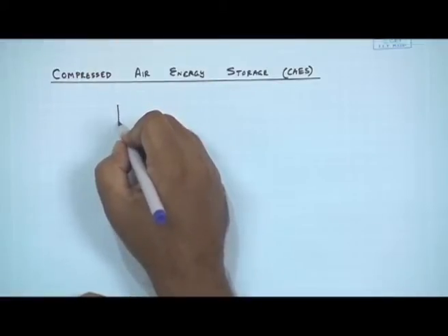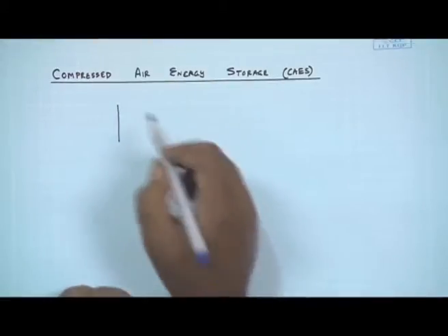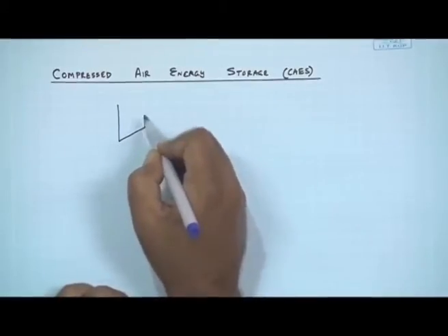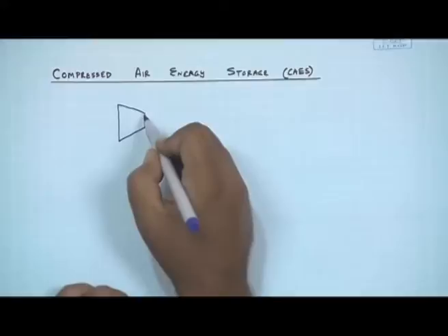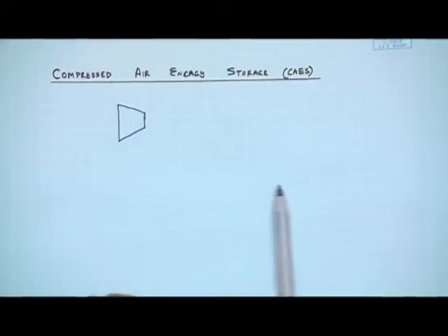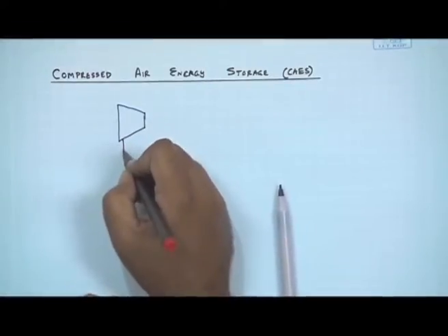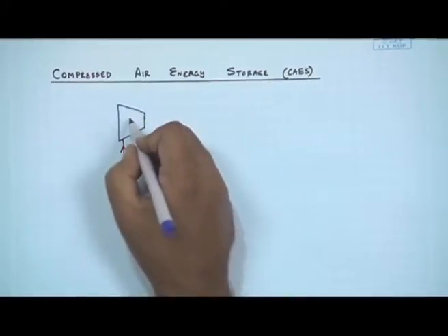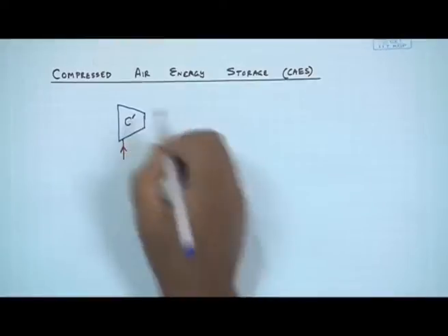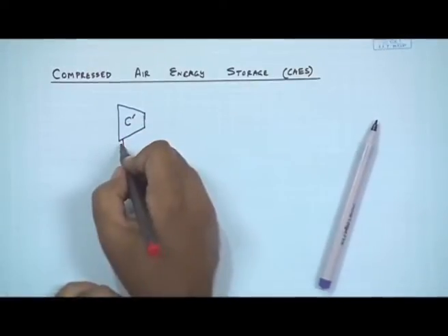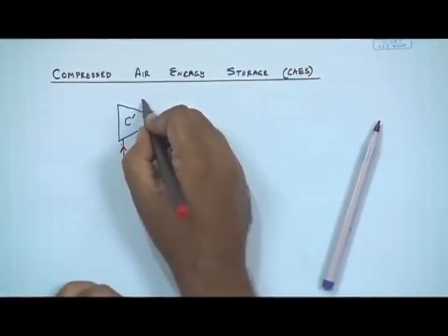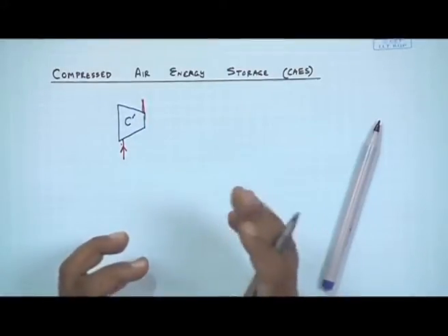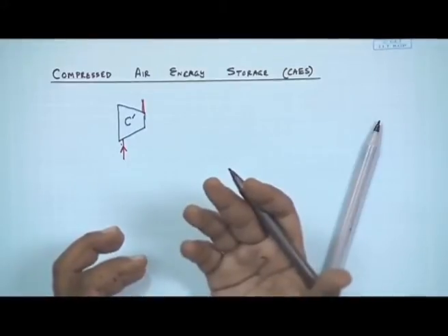In the gas turbine cycle, and you would have studied this in this course itself, the first thing that we have is a compressor into which air enters and is compressed, and when it comes out it comes out at a higher pressure, and because of the compression the temperature also is higher, has to be, right.